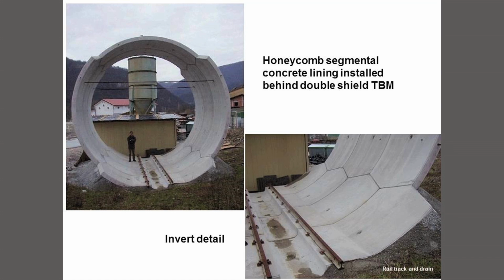And they didn't have rock burst in that tunnel. The tunnel was relatively shallow, perhaps maximum depth of 400 or 500 meters, going through a variety of rocks. They assessed the conditions along the 100 kilometers of tunnel that had to be built, and they decided that if they used machines with long telescopic shields, and installed immediately behind them shield concrete linings of the type illustrated here, they could go right through this at very high speed with minimal problems.